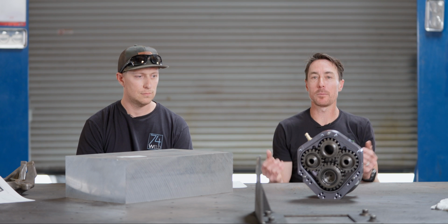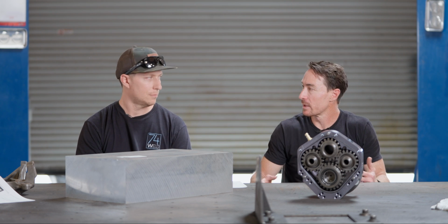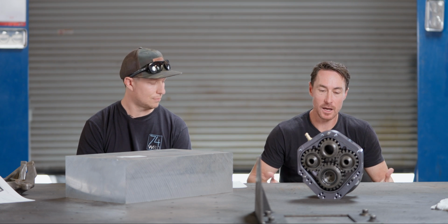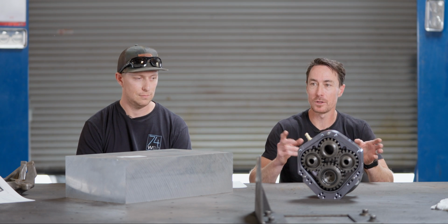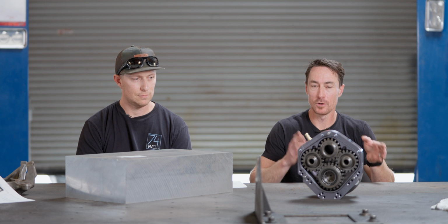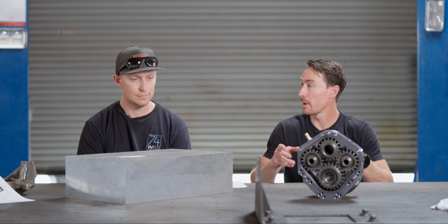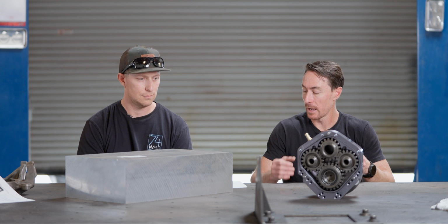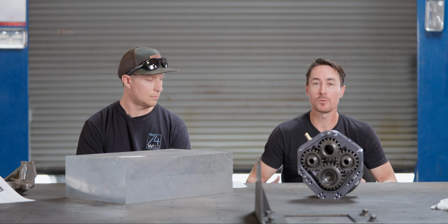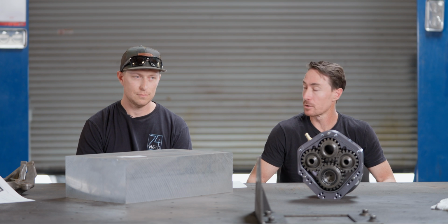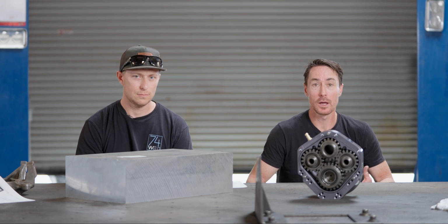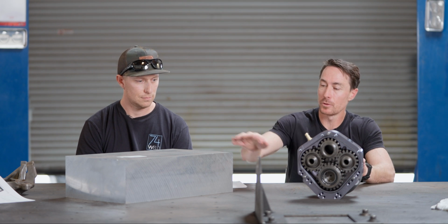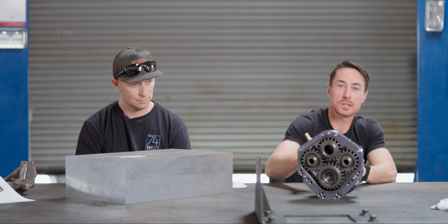So saying that 300M is the best material is like saying everything's a hammer. If you take that kind of approach, you're missing the nuances, you're ignoring certain properties that may or may not have a huge impact on the ultimate product. And what would you run for a wheel stud? Well, I would argue 4140 is a good choice because it does not work harden and it's still a strong material. So I'll circle back to 7075 versus 6061.